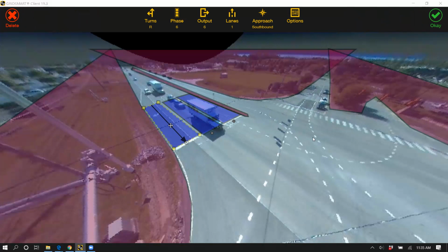Does the phase green eliminate the delay? Well, once phase 6 is being serviced, then yeah, it would recycle over from the beginning. It would start your cycle back over after phase 6 gapped out or timed out. Then it would be back to 0. And then if a vehicle pulled back in after the zone had cycled off of phase 6 in the controller, then it would be open again. Yeah, hopefully that answered your question.